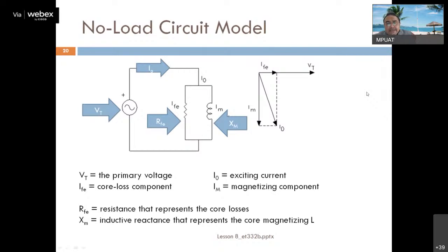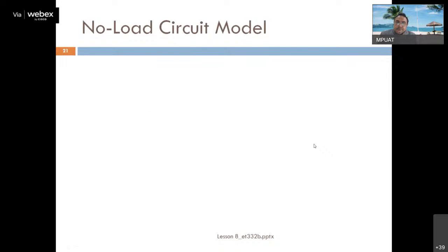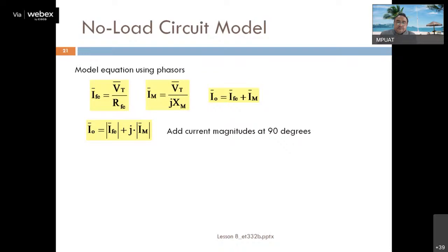So we have two components, RE and XM, two parallel branches, and that are being shown in the equivalent circuit of a transformer or practical transformer. Two currents, one is the magnetizing current and a core loss current. Okay, and this is the phasor diagram. So in phasors I can again represent all these things, that is IFV or IE simply. Most of the books write IE.